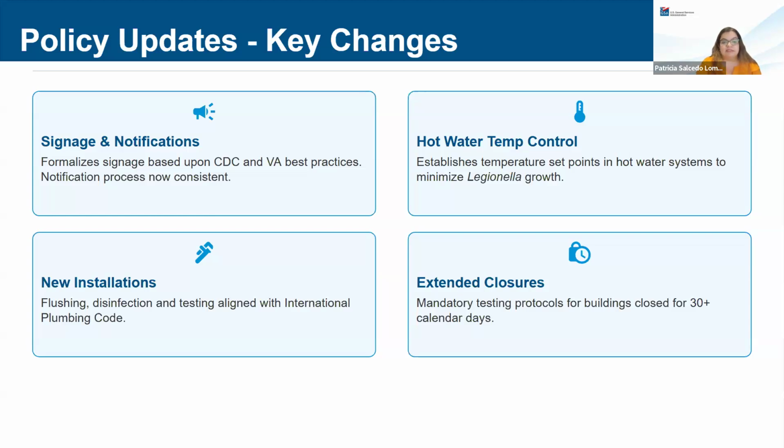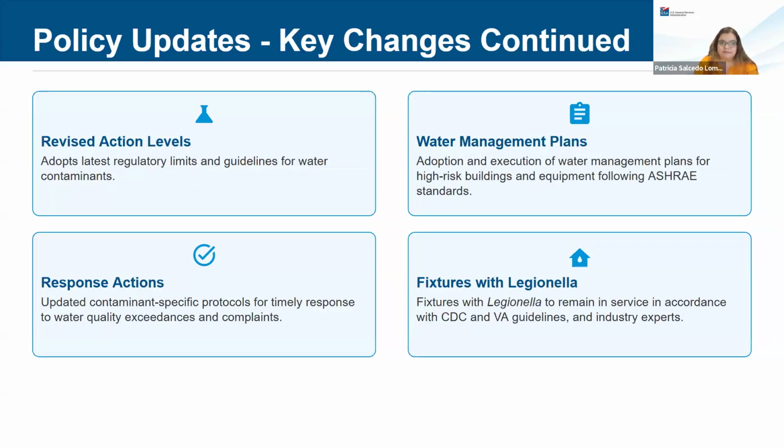When we do have new installations, there's flushing, disinfection, and testing aligned with the International Plumbing Code. As well as if there's at any time extended closures, there'll be mandatory testing protocols for buildings closed 30+ calendar days.